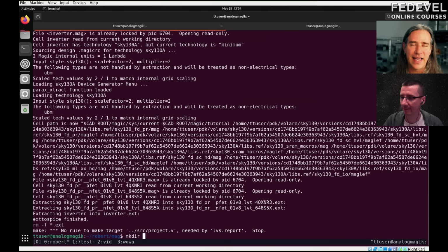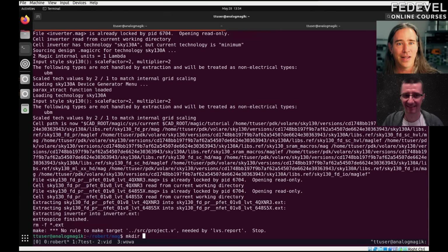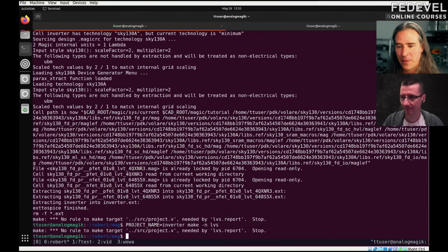So LVS is layout versus schematic. And the question is, did we actually wire it up like the schematic? If all the nets are connected correctly. So when I'm doing a DRC in KiCad in PCB new, it checks the schematic for equivalence at least. In this case, we could have wired it up completely wrong. No DRC errors, but the circuit just doesn't work. So let me not do this, but show you what the command would do here.